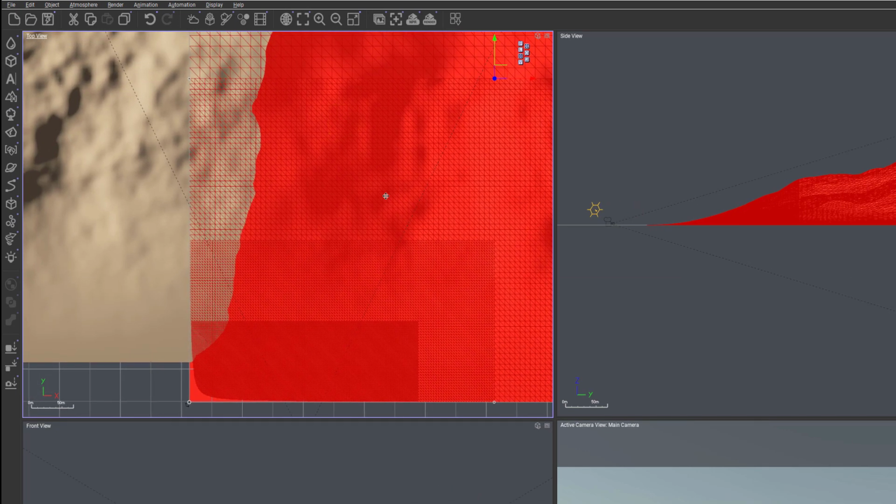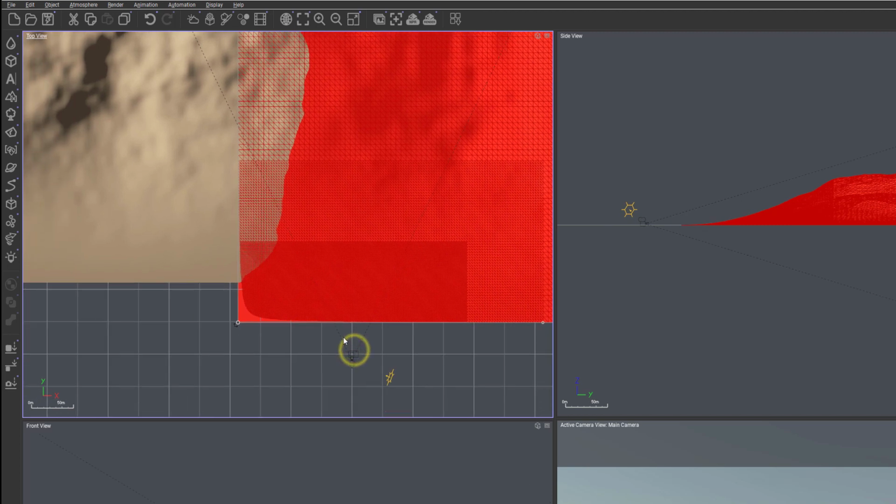Vue determines how close the terrain is to our camera and, based on this, builds a high resolution image, which is the terrain. If we take our camera and come closer and closer, because it's fractal based and procedural, we'll have more and more details on the terrain, and it's excellent. It's actually a very nice way to do it if you don't know how to position things. But in our case, this will take additional resources, because remember, if we move our terrain, it has more polygons, and the system needs to calculate all this stuff.